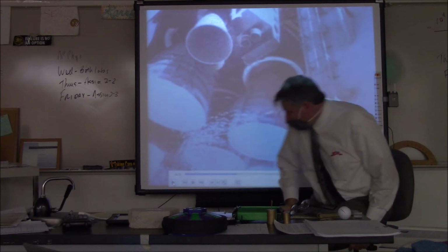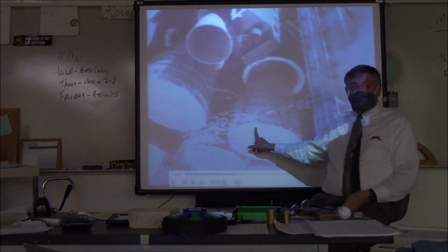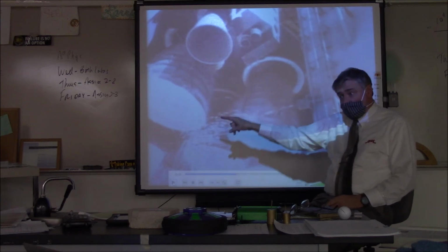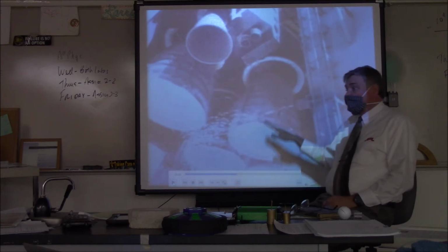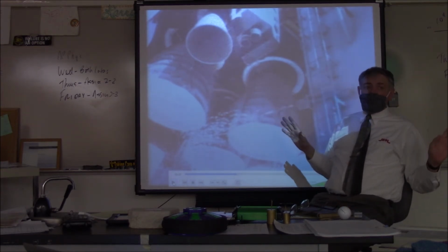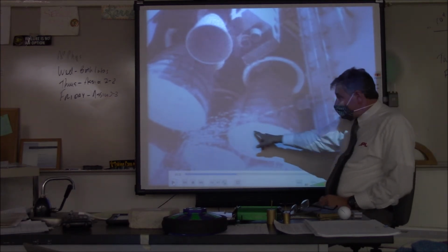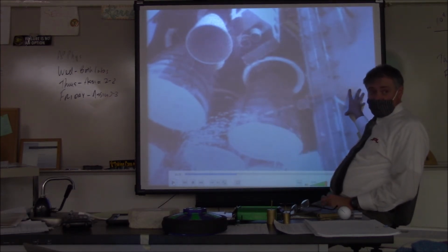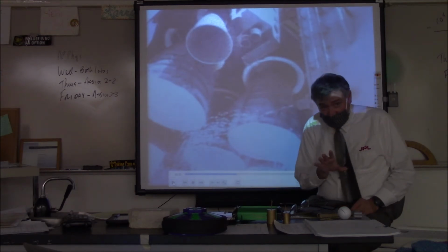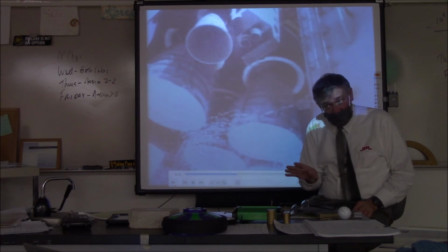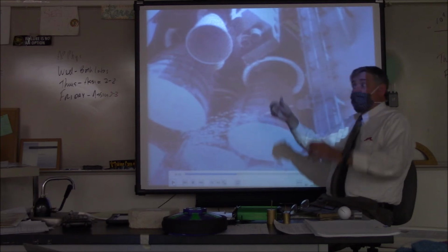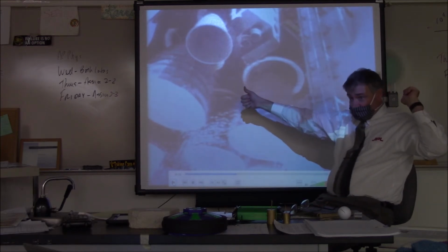Now, the other thing that happens about why they start these first is that these are run off mechanical pumps. So if there's a problem with one of these 3 engines, you can shut them down and go, okay, no big deal, let's try again. So they get these up and running first, and then they start those big solid rocket boosters, because once you start the solid rocket boosters, you can't shut them off. So they're firing these, making sure everything's cool, and then they fire up the big boys on the outside.